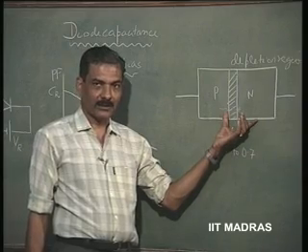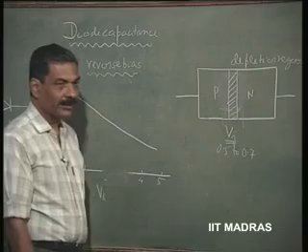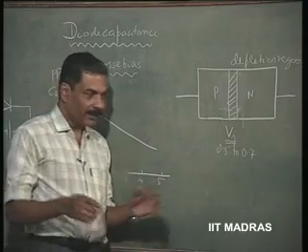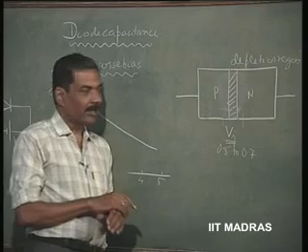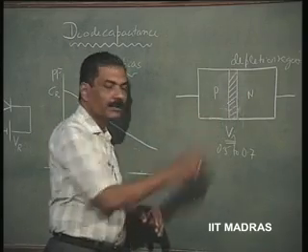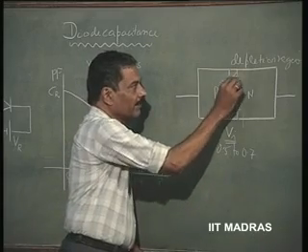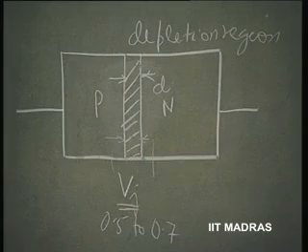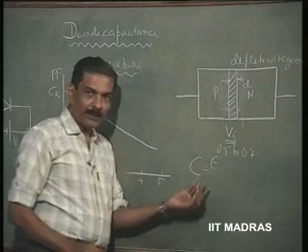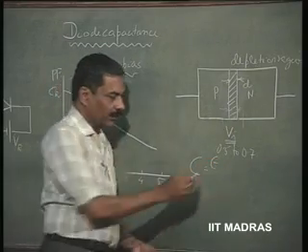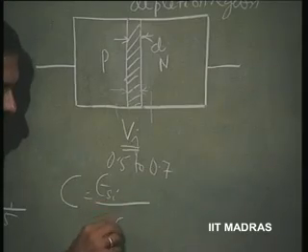but a capacitance really. Therefore, we can always say that a junction diode under reverse bias condition, apart from being considered, DC wise, as carrying only the reverse current, can also be considered to have a capacitance which is dependent upon this. So, if the depletion layer width is, let us say, d, then the capacitance is epsilon, where epsilon corresponds to that of silicon, divided by d, into area.